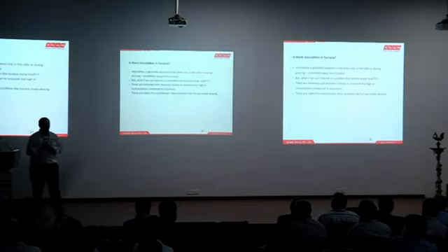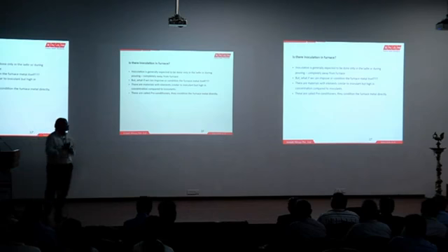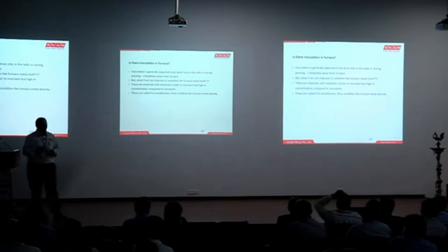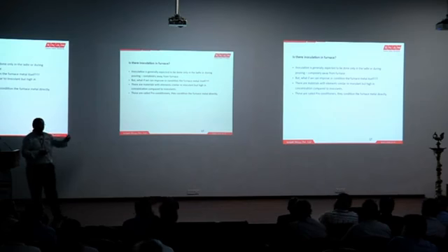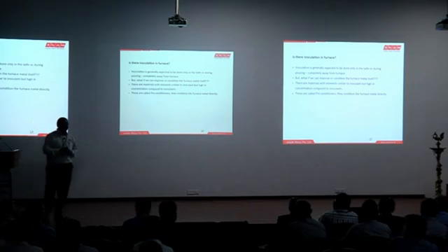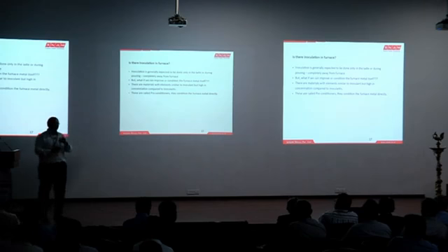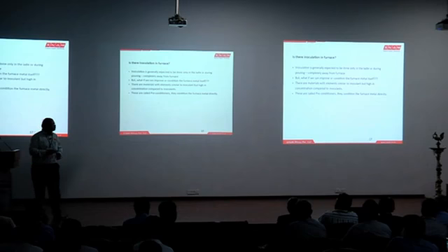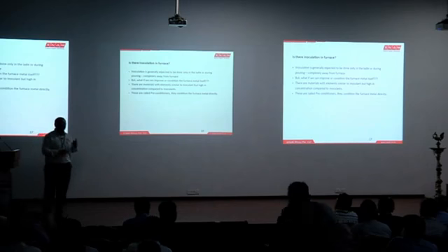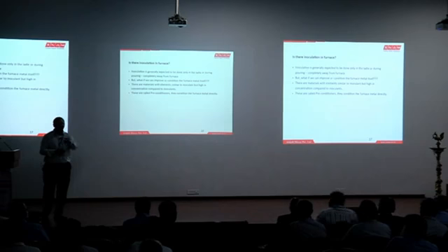Okay, we have been talking of inoculation in liquid metal after the furnace. Can we do inoculation at the furnace itself? Yes, it is possible. You can call it conditioning of the liquid metal. Whatever changes or demand of inoculation, or improved or varying levels of elements in the inoculation materials, have come up due to the varying potency of the raw material or the potency of the liquid metal itself. So if we can control the furnace metal directly, then you can actually work on the optimization of inoculation levels and the elements you want in your inoculant.